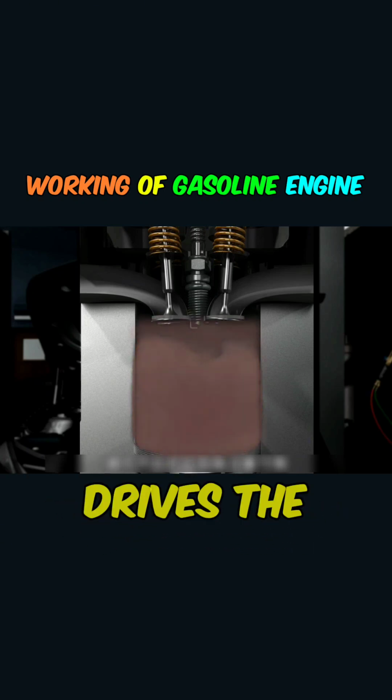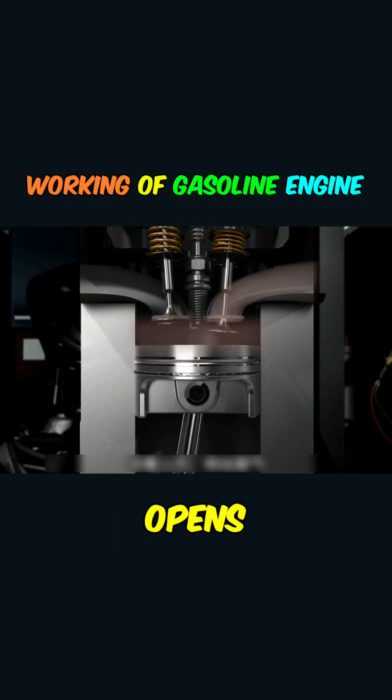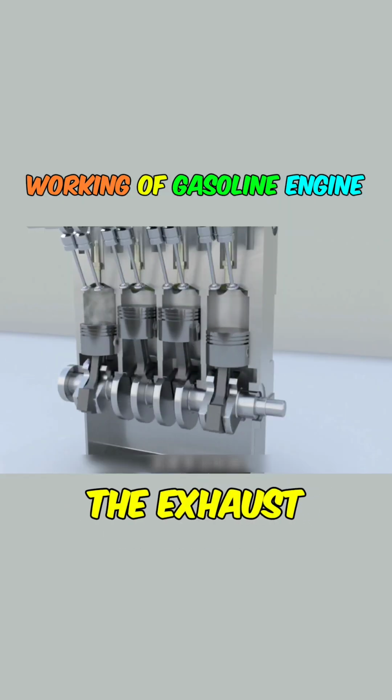An explosion occurs when a spark plug ignites the compressed mixture of gases, and the force from the explosion drives the piston downward, which is called a power stroke. Then the exhaust valve opens and the piston rises to expel the exhaust gas. This process is called the exhaust stroke.